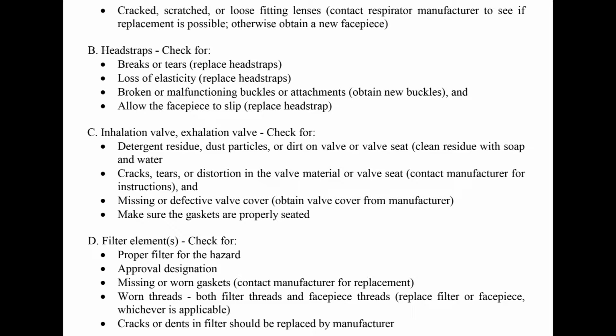Inhalation valve, exhalation valve. Check for detergent residue, dust particles, or dirt on valve or valve seat. Clean residue with soap and water. Cracks, tears, or distortion in the valve material or valve seat: contact manufacturer for instructions. Missing or defective valve cover: obtain valve cover from manufacturer.